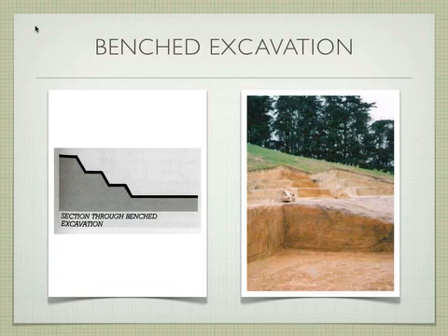Okay, and recognize these types of excavation and what you can use vary greatly on the type of soil that's used. In this particular example, because these sides are relatively steep, right, is it a cohesive or cohesionless soil? Cohesive soil, okay? This photo, same thing. It's a cohesive soil, right? Anytime you see these straight benches, okay?